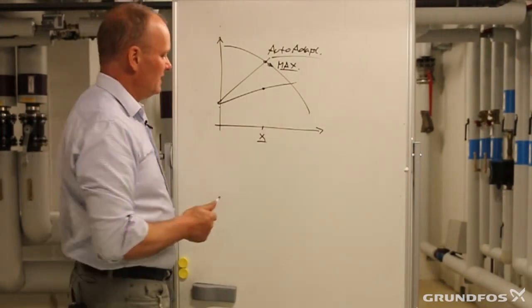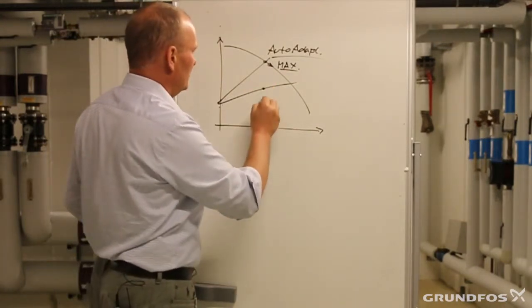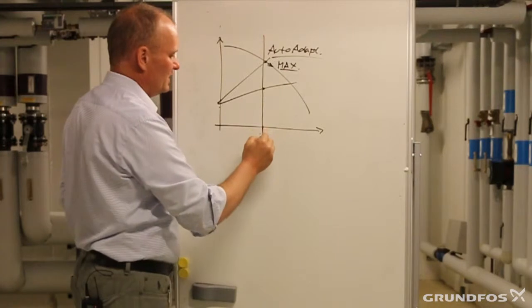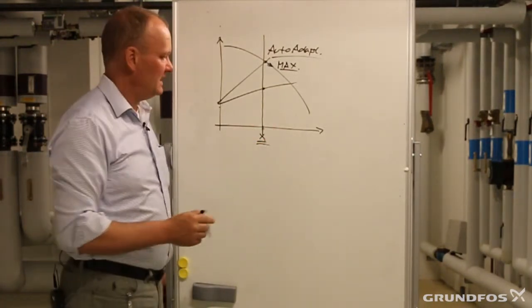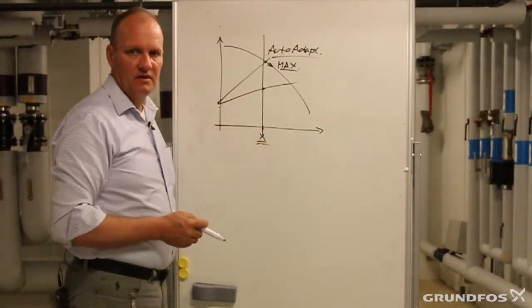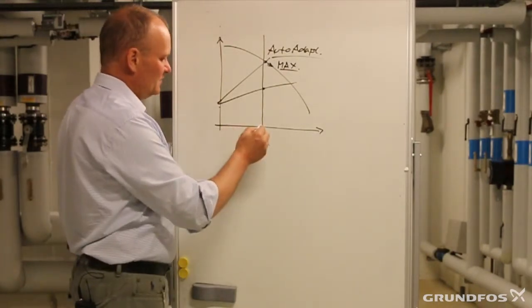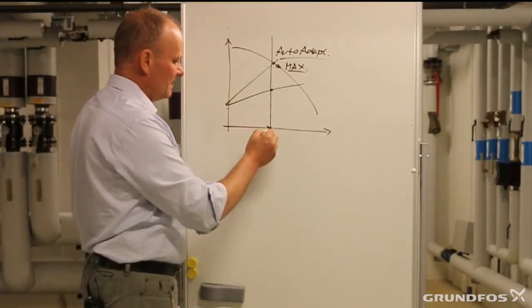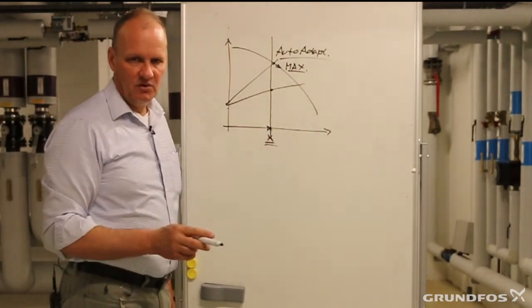Well, and then further on, we also have what we call flow limit. And that is where we can set a maximum limit to the pump that, okay, we have calculated that this is the amount of cubic meters per hour or gallons per minute we need. So we will accept you to move until this point and deliver this amount of flow, but nothing more.